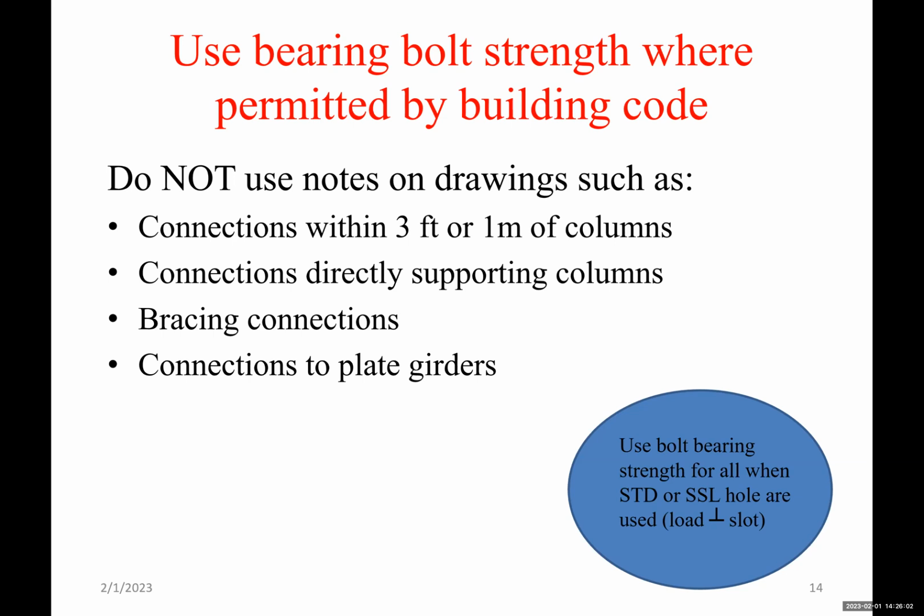Okay, so do not group the connections like this. Treat each connection as a connection, the way it is, depending on the forces that are on it, depending on the requirements that are needed for that connection.